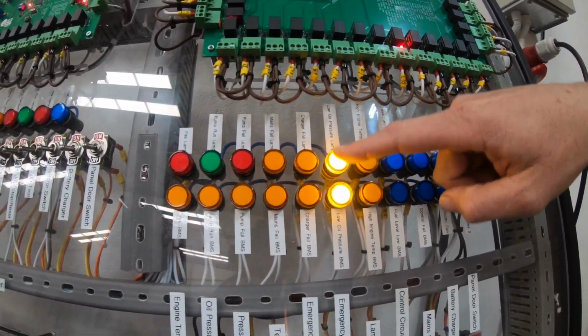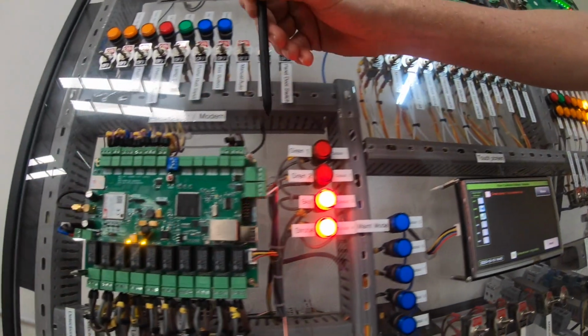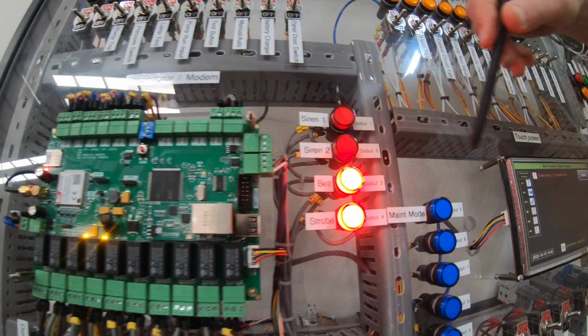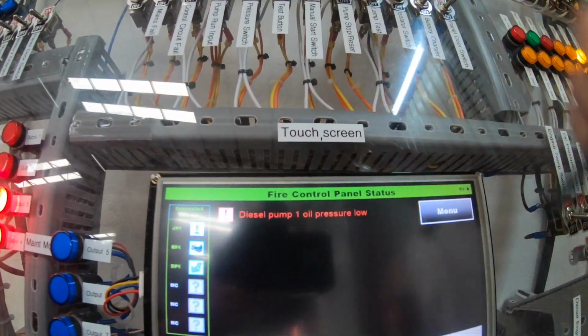Activates the outputs, the LEDs, the lamps. Go to the auxiliary, the annunciator. The auxiliary strobe and bell have activated. Come to the display. We've got diesel pump oil pressure low.